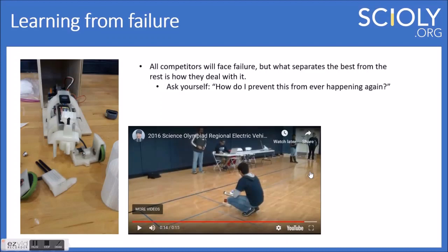So from there on, we always implemented a backup code system where if it realized, oh, I haven't gotten past that 8.5-meter mark, I need to give it a couple extra pushes, and the motor would flip on and get past the 8.5-meter mark, and then it would proceed into the target approaching part of the code, which is a big system of loops that we used.